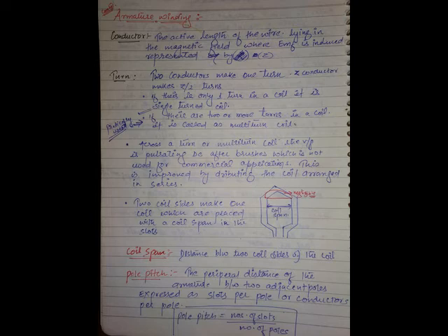So first, what is the relation between electrical and mechanical degrees? You can write like this: theta m, mechanical degrees, is equal to theta e by P by 2. Can we say that? So apply this formula to the first case. Theta m is equal to theta e. How many poles are there? 2 poles, 2 by 2, 1. Apply to the second case. 360 mechanical degrees. How many electrical degrees? 720. Apply. In place of theta e, place 720.